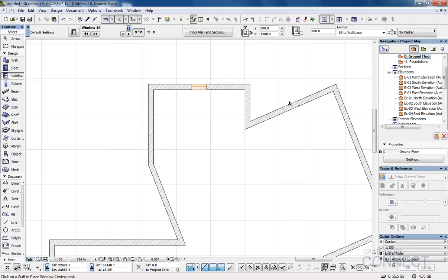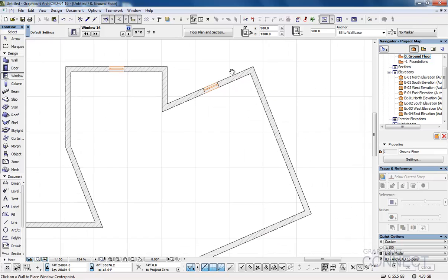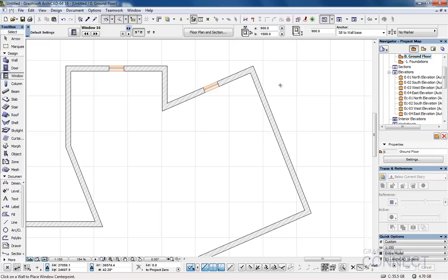I could do the same over here. Find the centre, tick, click, and that's that one placed. However, we want to move that on a little bit, so what I'll do is maybe change to a corner placement method. And what I'll also do is come down to the bottom here and use this little button to switch to distance. There's also other options to divide walls into divisions, percentages, or in this case distance of 225. In fact, we'll make it block dims, we'll make it 450.